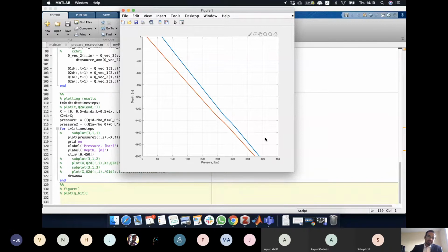When you keep your flow constant and your choke is plugged, you will have multiple wave reflections of this sort. And if you notice, the pressure profile keeps moving to the right-hand side, which means you're constantly increasing your bottom hole pressure because of the reflections.